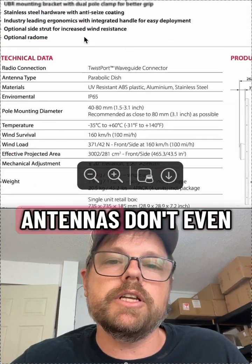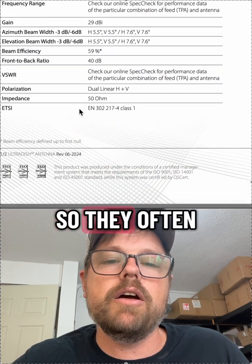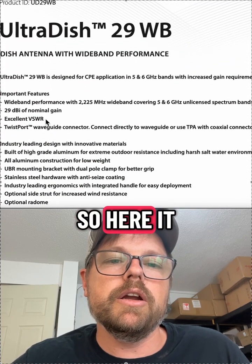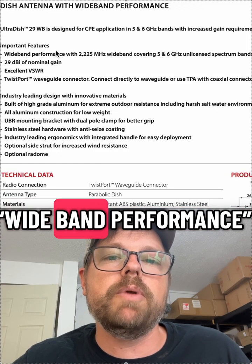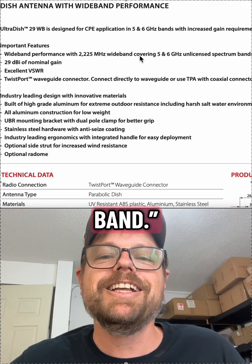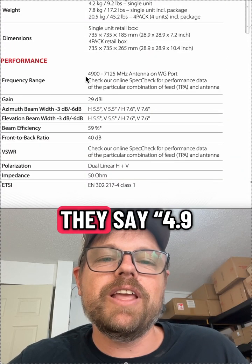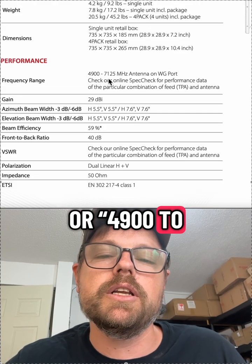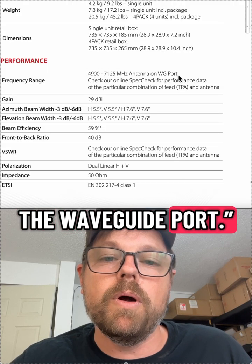Their 5 gigahertz antennas don't even cover the entire 5 gigahertz range. So they often confuse the frequency range of their antennas. So here it says 5 and 6 gigahertz unlicensed spectrum band, wideband performance, 2,225 megahertz wideband. The 5 and 6 gigahertz bands, they keep on saying this. Down here, they say 4.9 to 7.125 gigahertz, or 4,900 to 7,125 megahertz on the waveguide port.